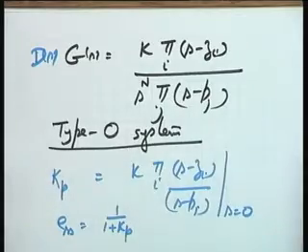So it means, please see that your type 0 system cannot meet high demands on steady state accuracy. It can at the most give you reasonable steady state behavior if the inputs are only the step inputs or the constant inputs. This should be very clear now. A type 0 system cannot meet high accuracy demands.